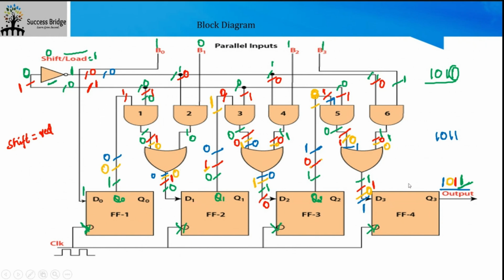So this is used in compressors. Actually, the LFSR concept also uses this in EDT compression. We'll be discussing it at compression time again. And we also use it in simulations, for parallel monitoring instead of serial in, serial out. Sometimes if serial in, serial out has an issue, we try to do parallel monitoring. Then we dump out parallel in and serial out patterns.